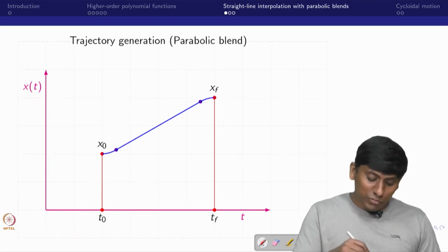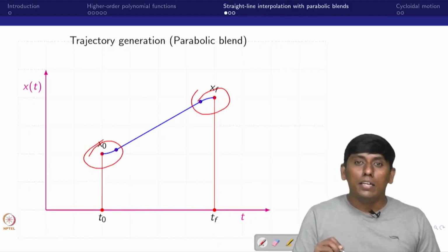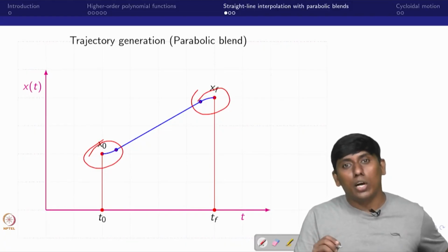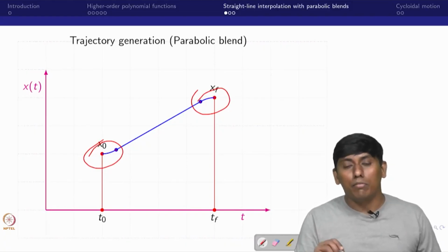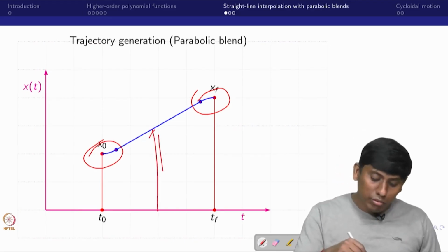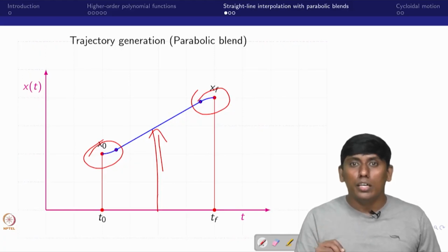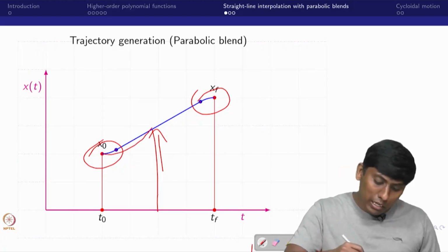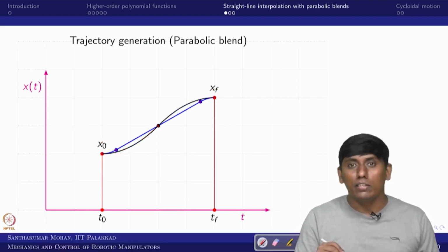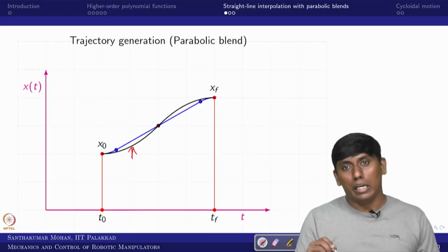Now what you can see, the starting point and the end point would be a smooth starting and ending. In the other way around, in the middle, wherever you can see, it is a smooth straight line, which is the shortest, best path which we expected, right? So in that sense, this is what you call a parabolic blend. Even this blend can be modified without a straight line. You can make a parabolic like this. Okay, so that is what we call uniform acceleration and deceleration, which is very smooth compared to this, because there is no straight line involved.